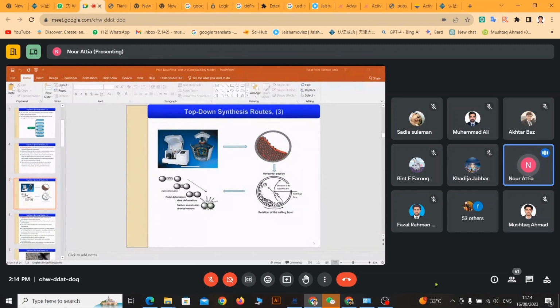And in this particular case, you have to put in some other soft material, because after breaking the material down to nanoscale, you have to cover it with some other material to separate it and avoid reaggregation. If you are preparing a nanomaterial for the first time using ball milling, you have to optimize the time and the frequency, because sometimes it will recombine again, right? So this is the main idea of using ball milling for the preparation of nanoscale material.